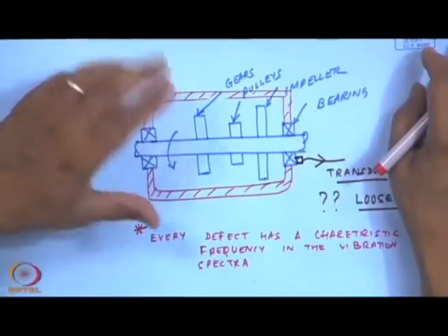When we studied bearing faults, we knew how the characteristic defect frequencies of bearings showed up in the spectra. We know about misalignments, how the axial components of the 2x vibration frequency showed up more prominently than the others. In gears, how side bands occur around the tooth meshing frequency.